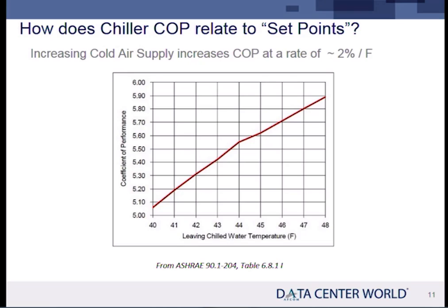I'm showing you a linear relationship here out of the ASHRAE catalog and one of the books. And you see it's also fairly linear within a certain range. It's not completely linear. I've been chased around on this before. But we have to make some assumptions. And for all practical purposes, you can assume it's fairly linear. You're going to get about 3.5% efficiency improvement in your chiller for about every 1.8 degrees Fahrenheit. Those are tough numbers to remember. But you can think of it as a percent per degree, which is not a bad idea.